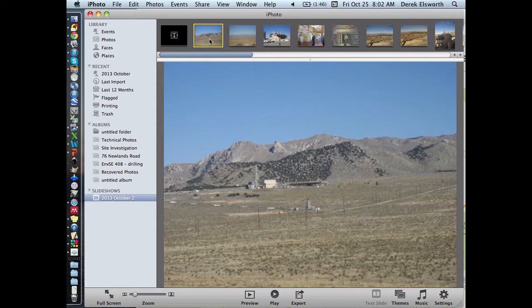If you go down a couple of kilometers, Marcellus is at about 9,000 feet, so that's basically 3 kilometers. So it should be 3 times 25 plus surface temperature, which is 20 degrees centigrade. That should be close to 100 degrees C at that depth, a little less, maybe 80. If the fluids you produce from Marcellus had the heat taken out of them, you could scavenge that. That's not very useful for Marcellus because it's so tight that you don't get much flow rate volume.